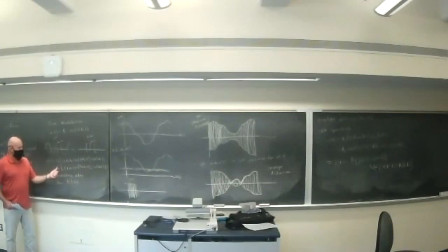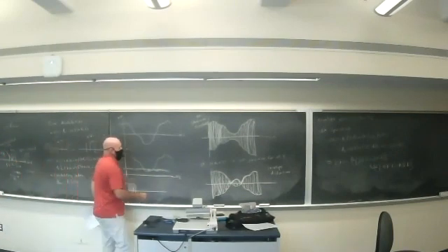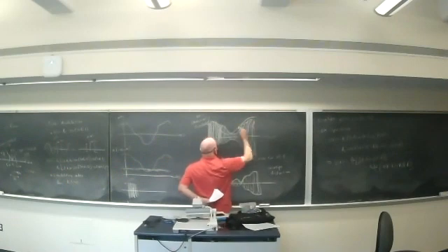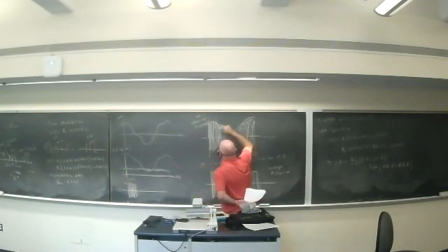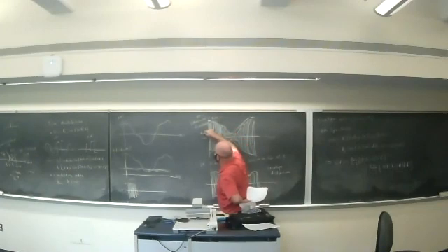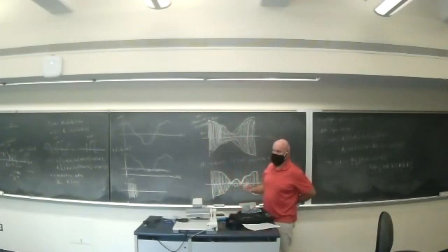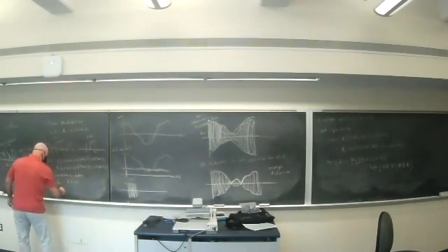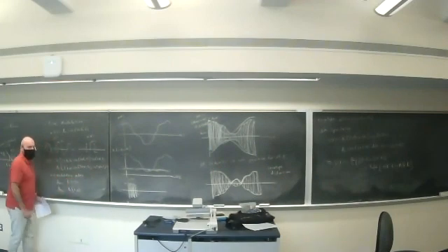If you were looking at the modulated waveform, you would have this low frequency tone and then the high frequency carrier, and this Ac times 1 plus mu is going to be A max, and then this value we'll call A min, subscript m-i-n. So the minimum value in the envelope is Ac times 1 minus mu. That's when the cosine is -1.